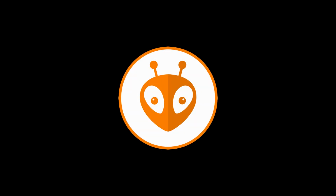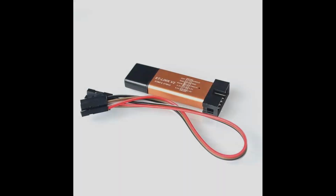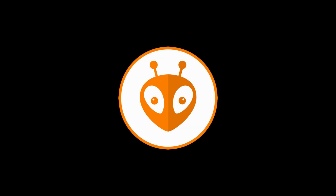Finally, if you want to use this with PlatformIO, you can use this set of configurations. This is a super easy way to start uploading code, but it isn't the most convenient. You may want to invest in an ST-Link V2 as it is very fast, allows for chip debugging, and it can upload code without needing to press reset. This setup works very well with PlatformIO, and I will have a more detailed video about that coming soon.